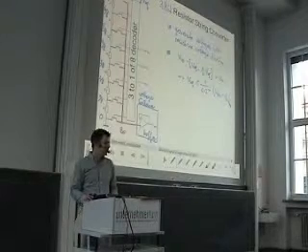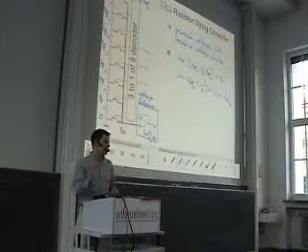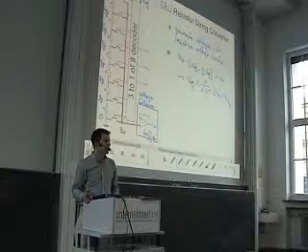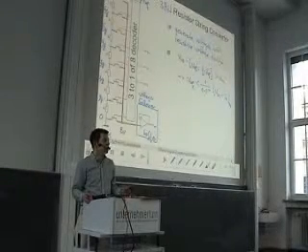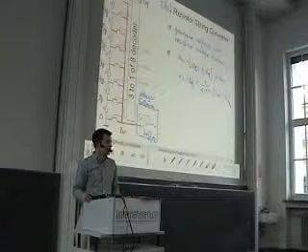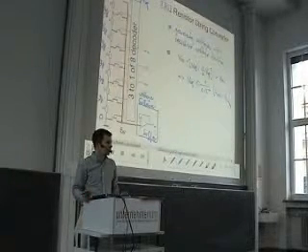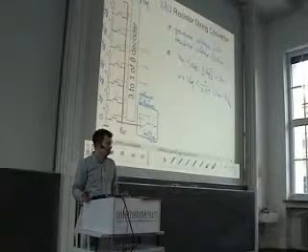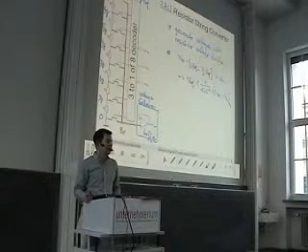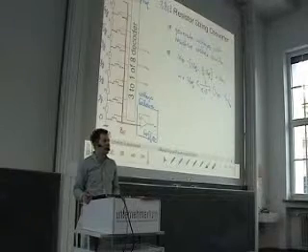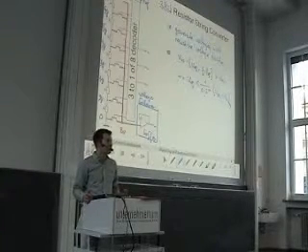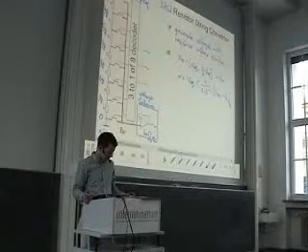So what you can do here is that you either mix NMOS and PMOS, or that you use complete transmission gates that can switch both small and high voltages. And the price for using transmission gates, we will see this on the next slides, is of course that we have higher parasitic capacitance, so we will slow down the circuit by doing this. Okay.